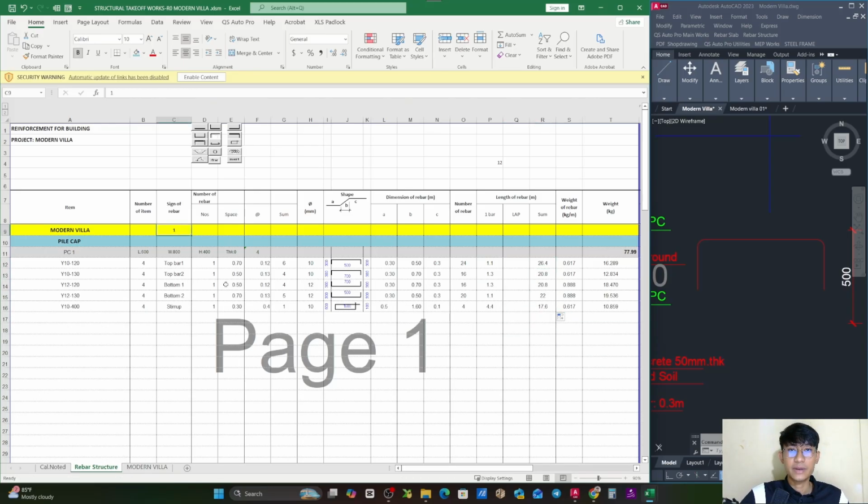Later on, based on the construction, sometimes we need the wastage, based on the tender, or the instruction from the client or the consultant, whatever they want. So all you need to type is, if you need 5%, just put 105, and then click enter. Perfect. Now the quantity will add 5% on top of our net quantity.